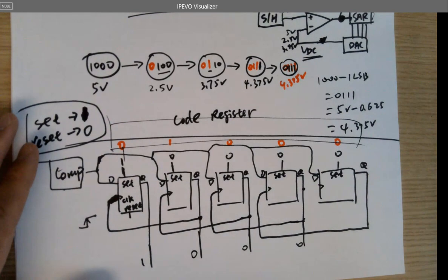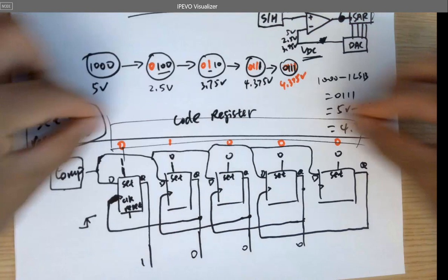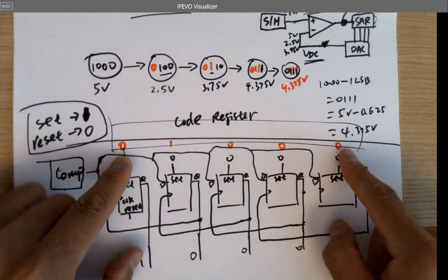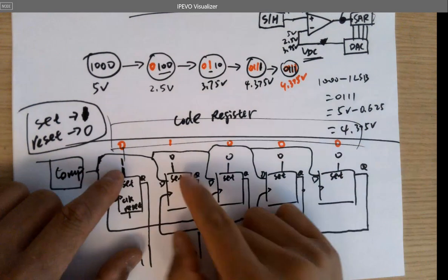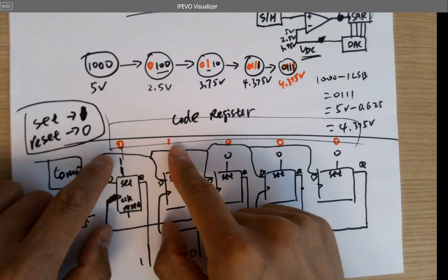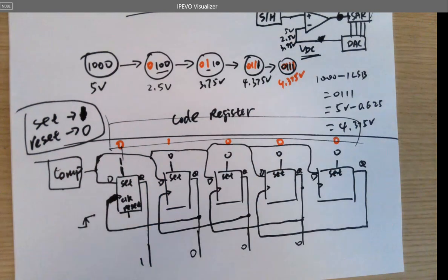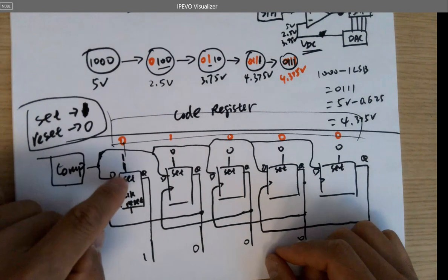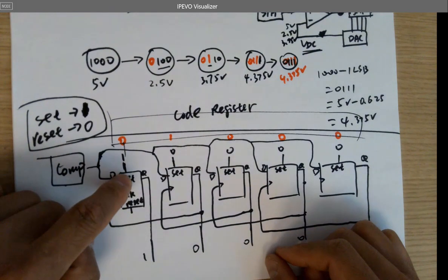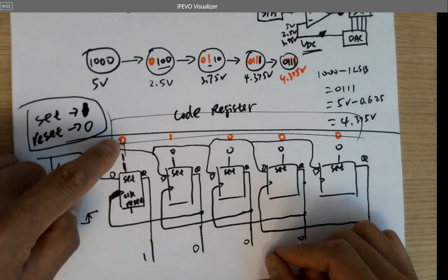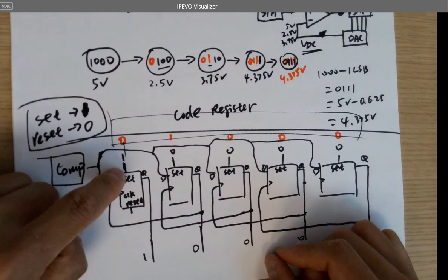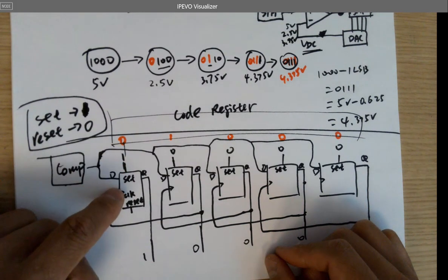So at one moment, the circuit on the top, the mystery circuit on the top, is able to shift that 5-bit digital data to the right by 1 bit, right? So 1 will be here, and then it's being replaced by a 0 because it's just simply shifting. What's going to happen? So this one won't be set anymore, and instead it's being released because I'm putting a 0 on the set, so I'm not turning on the set function. So this one becomes a D flip-flop. It's going to work, right? So this is going to be a functioning D flip-flop.